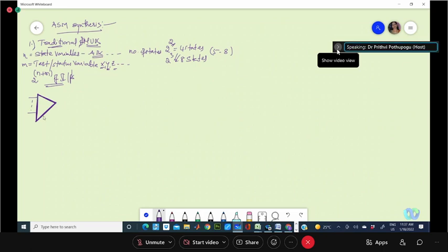And when we select the state variables, these become the selection lines, A, B, C, and so on. Based on which state you are in, that defines what should be your value, or what should be the next state your design will go to. Okay, this happens to be a sort of lookup, a derivation of a lookup table.